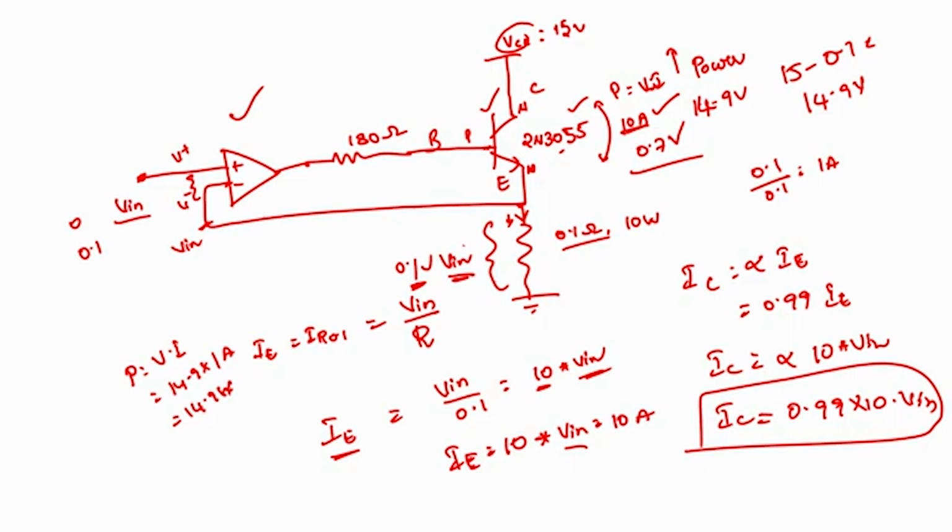When you look into the data sheet, it gives you the power dissipation factor, which gives you the relation between the wattage and the temperature generation, right. Based upon that, we can get a relation between the power and the degree. Now, if I increase the voltage to 0.5, one thing is clear: if the power is higher, as a result the temperature generated on top of the transistor will also be higher.